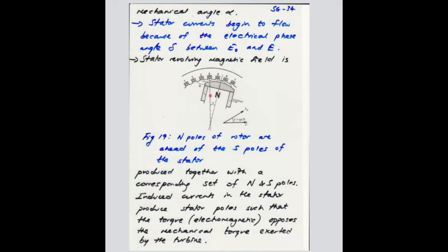So now, the mechanical torque is pushing the rotor forward, advancing the rotor with respect to the axis of the stator pole, and hence the currents are induced in such a way that if this is a north side, you will have a south side on this side, such that the field lines are pulling the rotor backward, trying to reduce that angle back to zero, right?